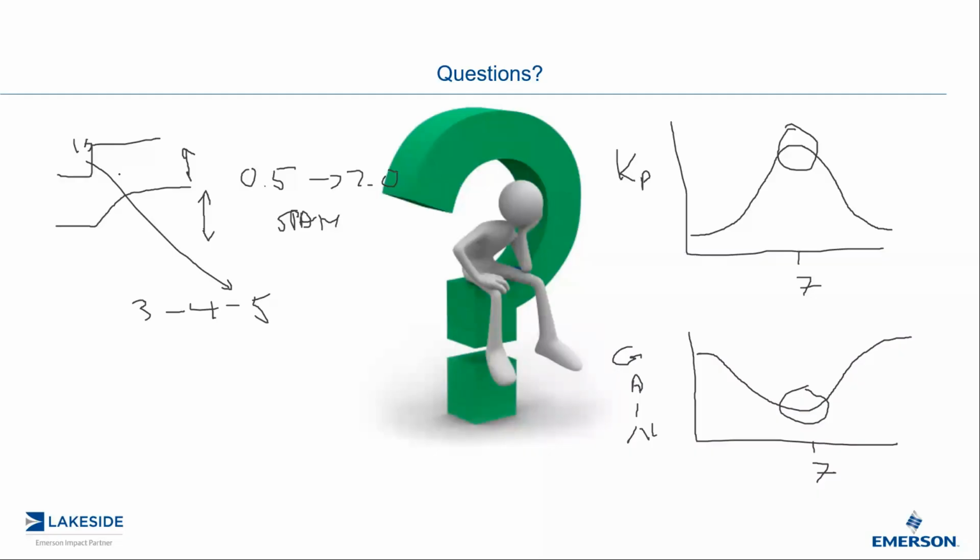It is anywhere between 0.25 to 0.5% change. That's the minimum precision of a very good pneumatic control valve. It could be worse, but 0.25 to 0.5%. So putting in adaptive tuning may help, but at the end of the day, you're still bound by that minimum valve precision. I would probably look more at the valve sizing.